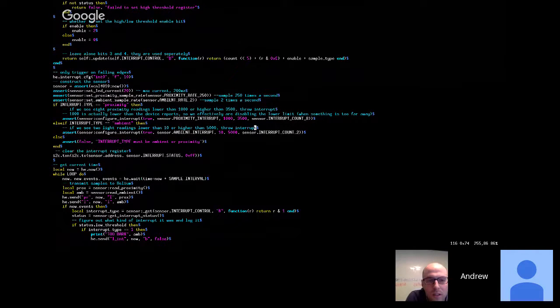Nice. And then obviously in ambient, we do something similar, except we have different values. 10 for low light, which is what, when I put my finger over it, you saw it say it was only 3, and then 5,000 for too high. I believe these might be in lux. I don't know. Again, I don't remember off the top of my head. I just read out the register that it tells me to read out right now. And then I say I have to see 2 of those, and that's how we get both interrupts.